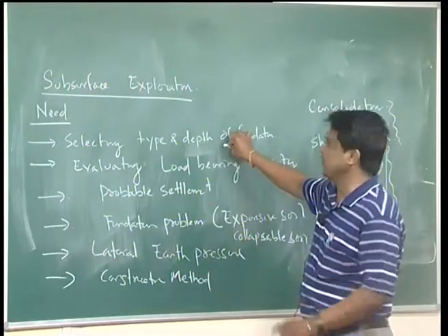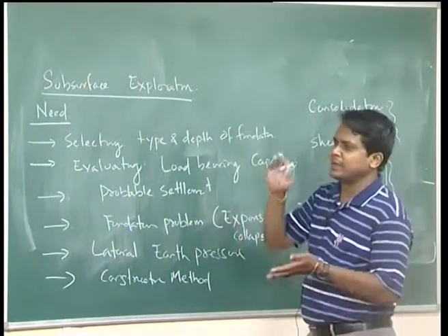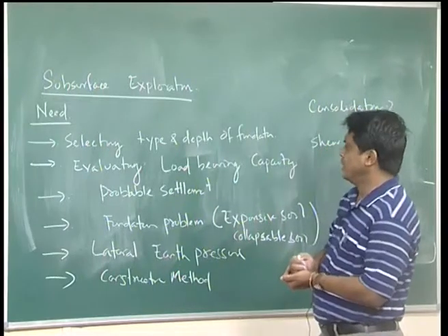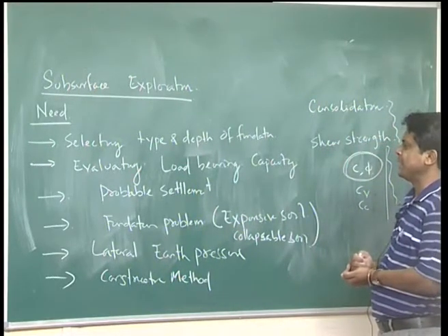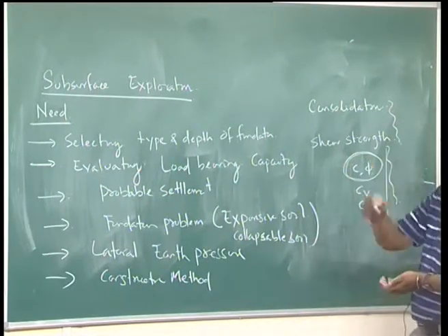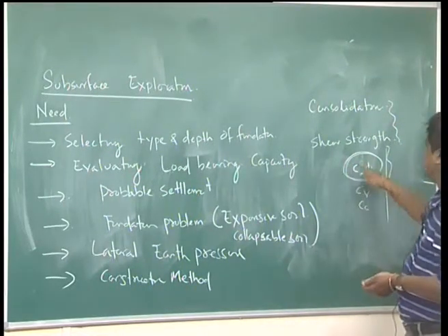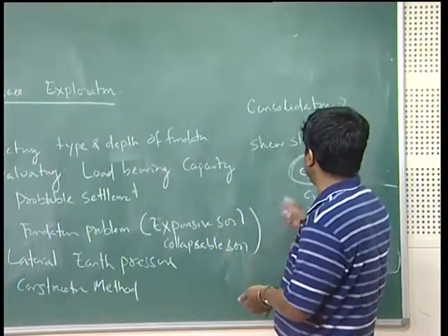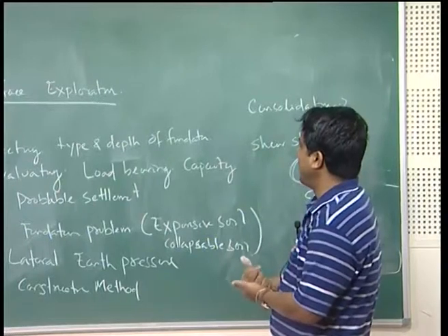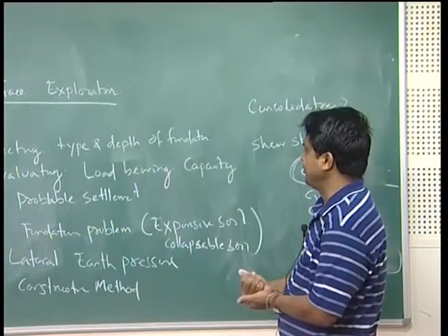What type of foundation you are supposed to choose and what is the depth, number 1. Number 2, how much load is going to be taken by this foundation. With the help of subsoil exploration, you can find these parameters. With these parameters, you can find how much load this footing can take.